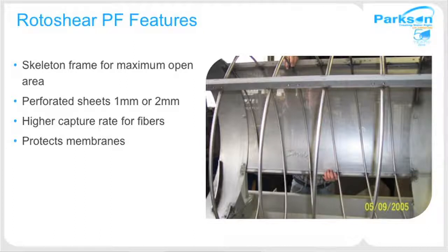It uses a skeleton frame for maximizing the open area on the perforated plates, and we offer 1 millimeter or 2 millimeter openings. And it definitely has higher capture rates for fibrous material, and it is typically, again, used for protecting membranes.